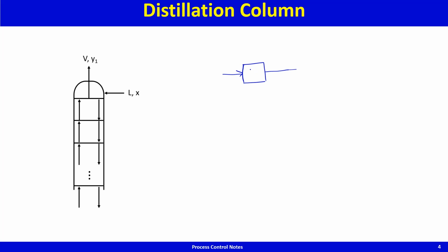And let us just say this is G, the transfer function relating the change in vapor composition due to a change in the liquid flowing into that tray. So there's a tray, there's what's leaving the tray, there's what's entering the tray, and we are saying the transfer function relating this to that is this guy, GVL. Relating L to Y, the transfer function relating L to Y is GVL. Effect of the liquid rate into a tray on the vapor mole fraction. Okay.